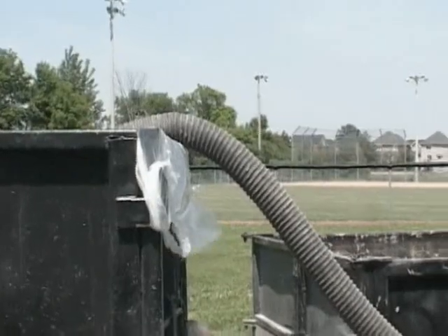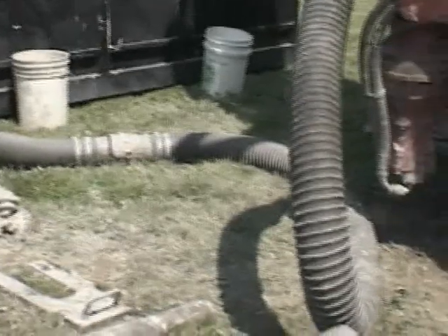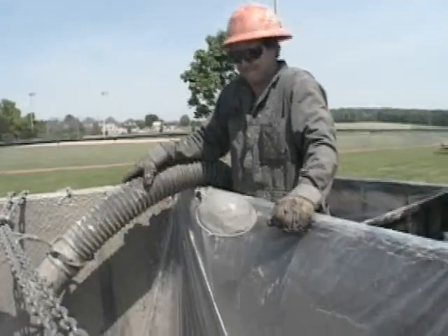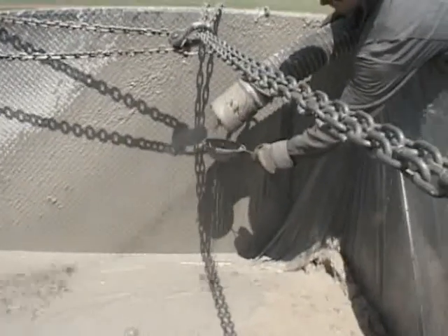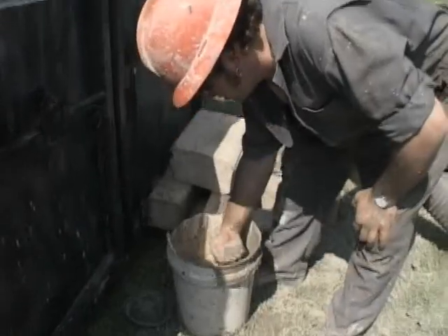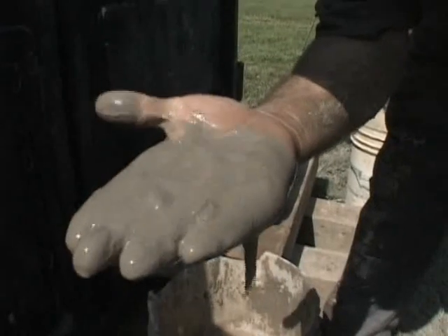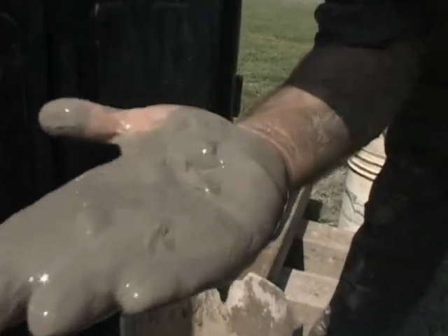The large metal bin is being used on this job site to contain the cuttings. This keeps the new well location pristine and as undisturbed as possible. The bin will be removed when drilling is completed. The drilling technician collects cutting samples of the formation at the discharge. These samples are clean and representative of the geology, and facilitate proper record keeping as per Regulation 903.